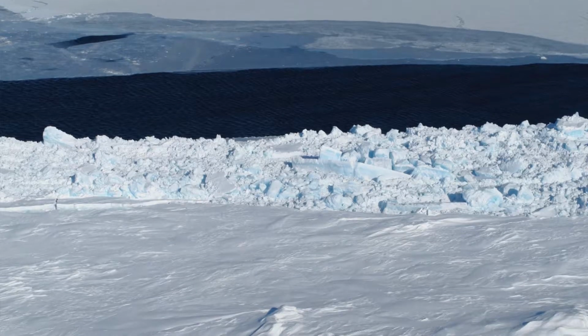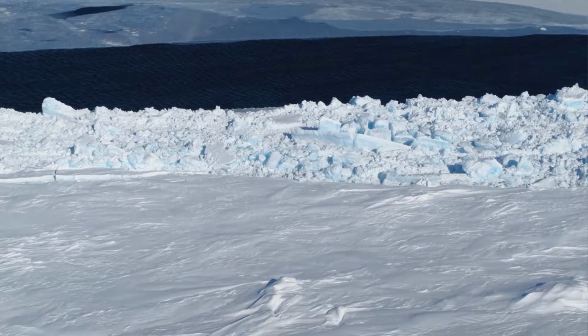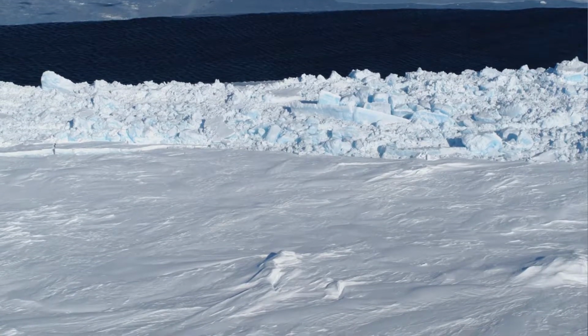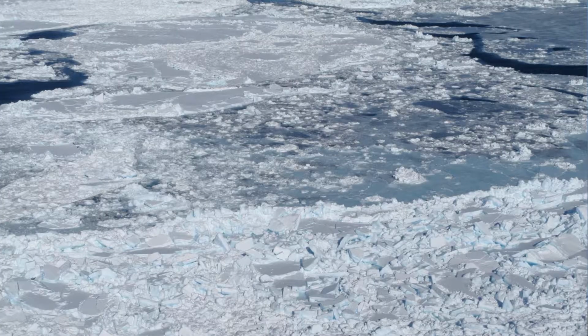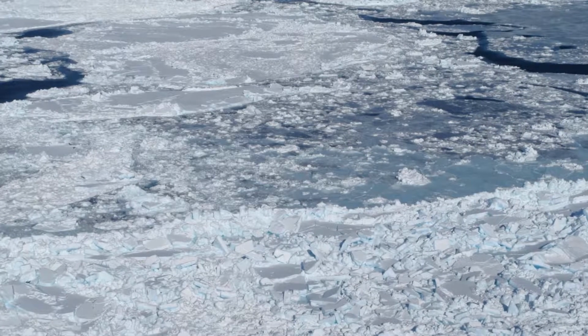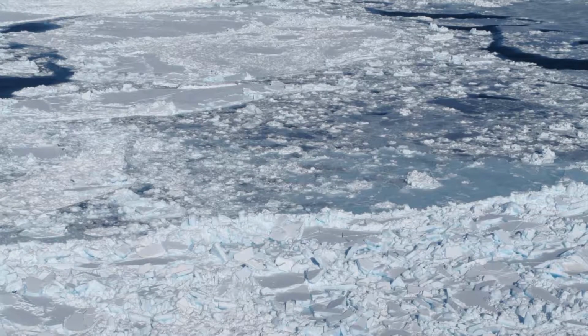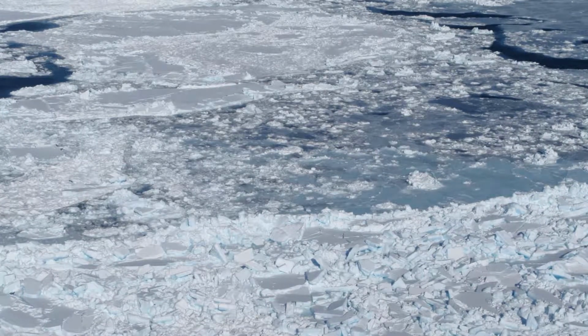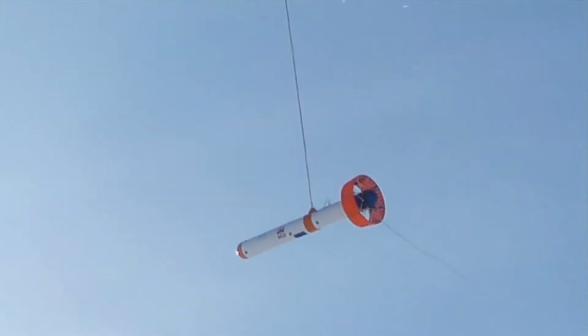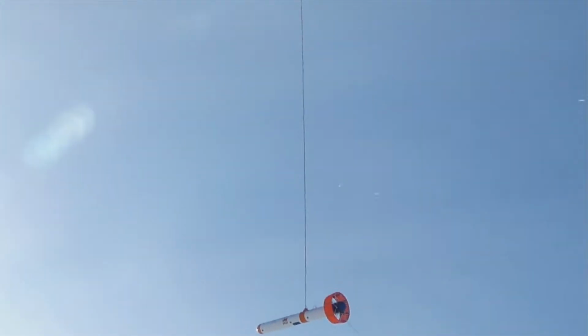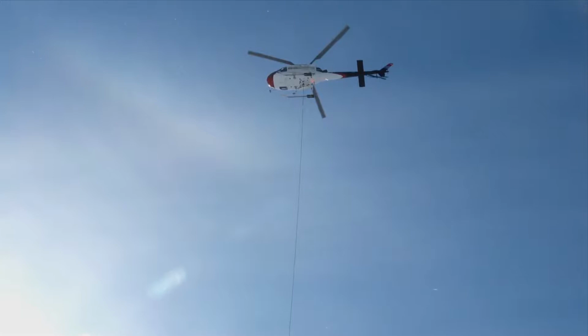If the ice is really thick, the ocean is really far away from the bird, and we can measure that. When the ice is really thin, the ocean is effectively closer to the bird, so that the bird measures the position of the bottom of the ice. And then we have a laser mounted on the bird that measures the position of the top of the ice. We subtract those two, the bottom from the top, and we get the total thickness.